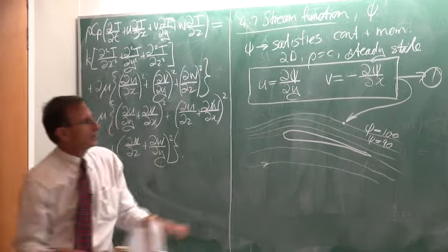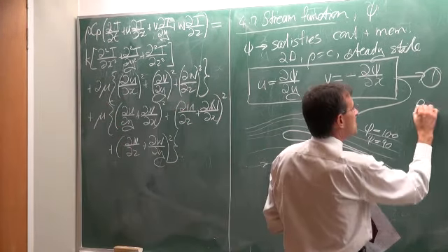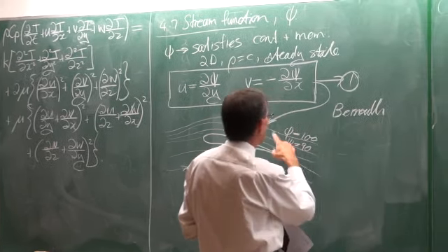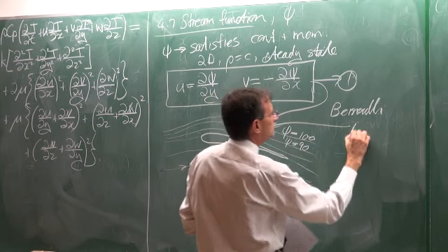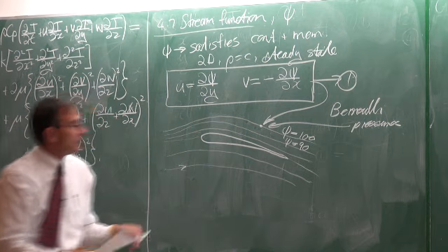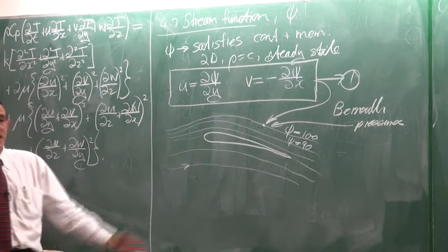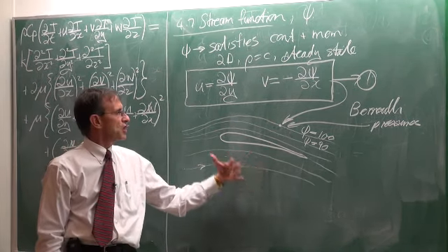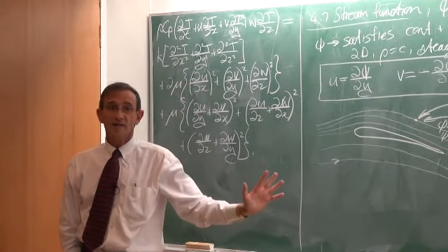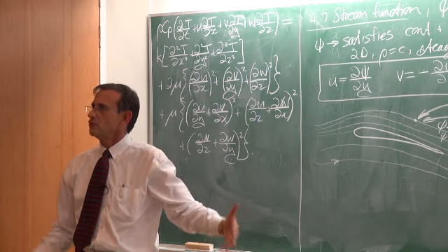And again, if you would then take into consideration the Bernoulli equation, then you can also get the pressures at all the points. And with that, you can get the pressure on this side and you can get the pressures on that side. And once you have that, you've got the lift on the aeroplane wing.